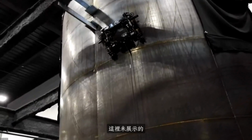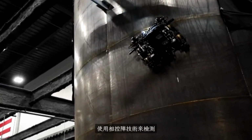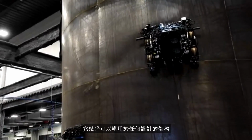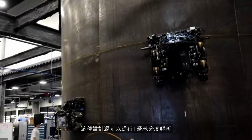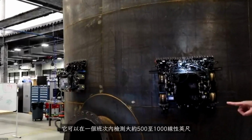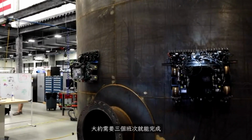Also, not shown here, a very similar robot to this has a weld inspection apparatus on the front of it using phased array for nominal thicknesses of a 1/4 inch through 8 inches thick. So it covers a wide range of all types of carbon steel material. It'll work on just about any tank design that's out there. This design can also do 1 millimeter indexed resolution, so very, very high resolution. And it covers roughly 500 linear feet up to about 1,000 linear feet per shift. So on a 100-foot tank, that could be done in roughly 3 shifts.